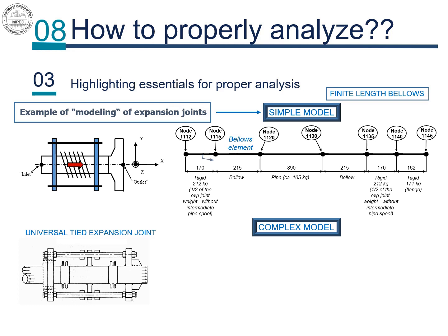Also, from node 1115 to 1119, where 1119 is a C node, a rigid weightless element is defined that is tied with node 1120, so that Y direction and Z direction translational movement is allowed, as well as torsional rotation, while all other movement between the node and a C node has been fully restrained. Simple models should only be used where the tie bars are either guaranteed to be carrying tension, or have nuts on either side of the flange so they could also carry compression if needed.